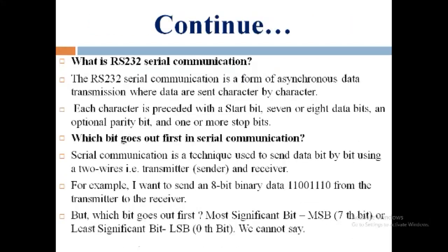Then, what is RS-232 serial communication? RS-232 serial communication is a form of asynchronous data transmission where data are sent character by character. Each character is preceded with a start bit, 7 or 8 data bits, an optional parity bit and one or more stop bits.